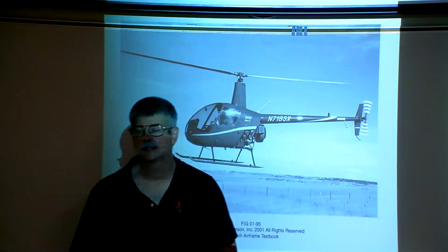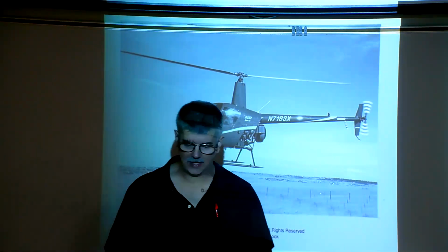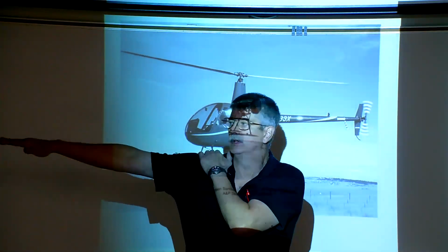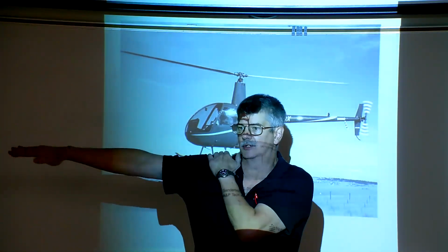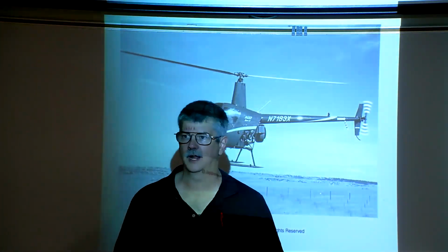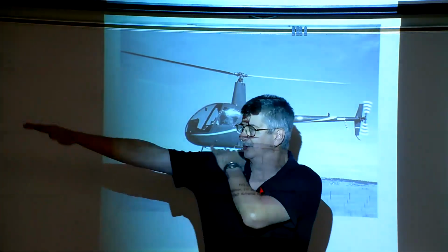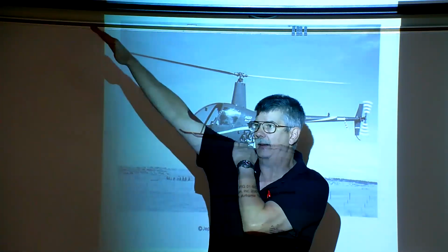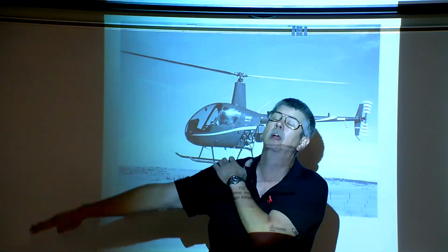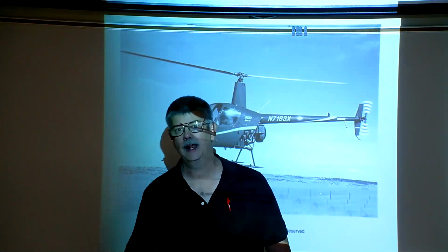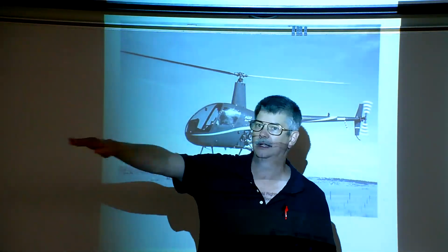Early days, they made what was known as a rigid rotor. A rigid rotor only allowed the blade to pitch, okay? But as we saw yesterday, there's a lot of other forces. There's forces that try to bend the flaps or bend the rotor blade up and down, which then makes the blades want to lead and lag.